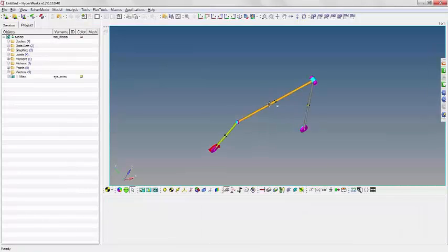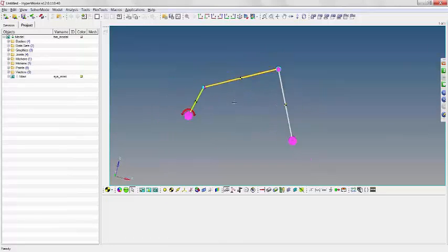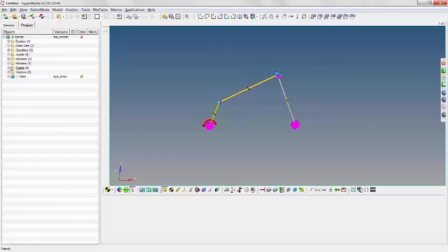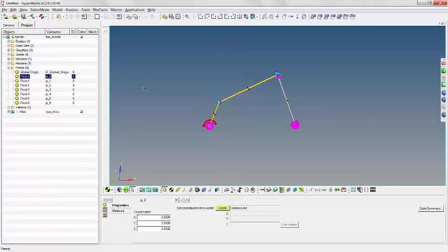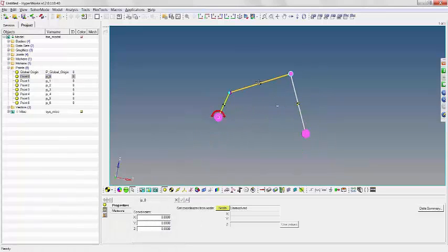This is the model which we are going to build now. As I said, we need points, bodies, and some explicit graphics to see the animation and how it works, and we need joints and motion, etc. Here are the points we have. Now let's start with building the points. Basically we have three bodies other than the ground body. We also have a ground body and a global coordinate system, you can see here.